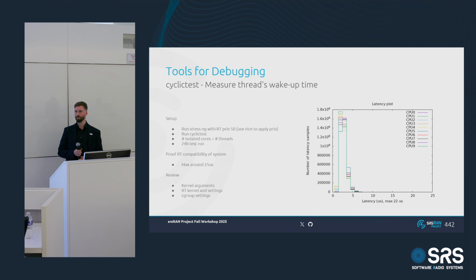One user can select eCPRI, another user can select another interface. What we are supporting is O-RAN fronthaul 7.2A and Split 8 currently. Split 8 is a version where you send IQ baseband over the link to a software-defined radio, for example.